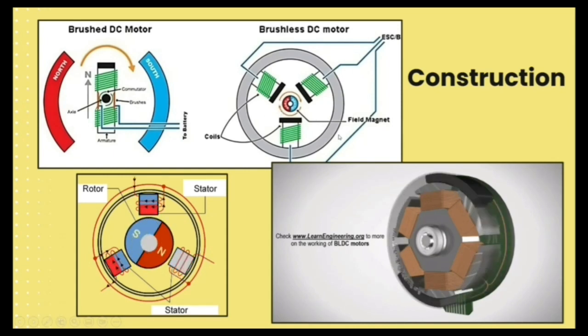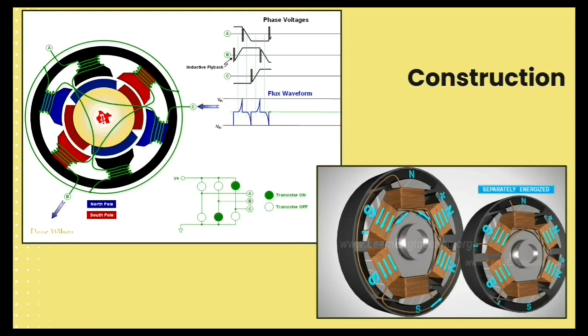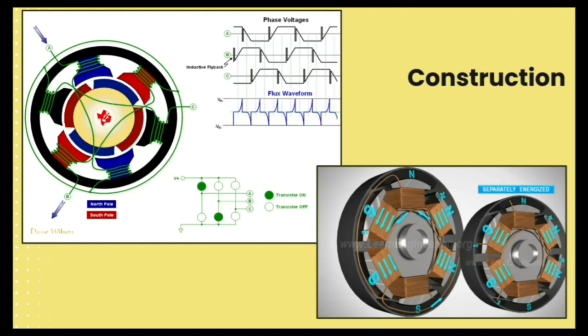We explained how we energize each coil, but how do we construct it, how do we energize coils from time to time? Sometimes it's A or B and B or C, and it's converted to B and C, A and C. How does it move, how is it energized at different times? For that we use sensors. That's why we said these BLDC motors were built after the semiconductor generation, because to build sensors we need transistors.